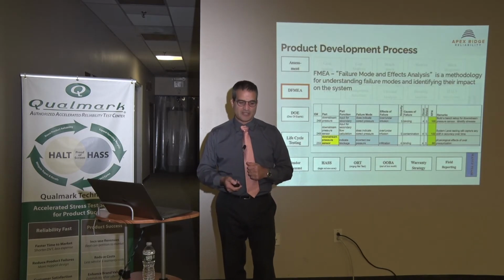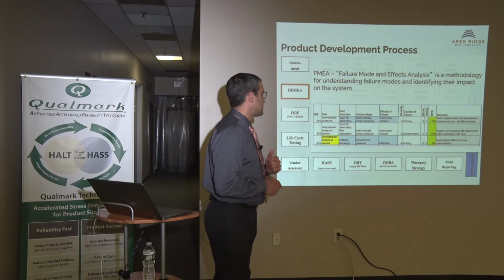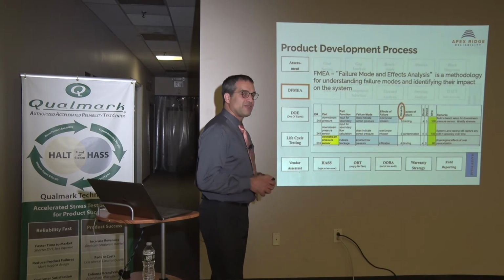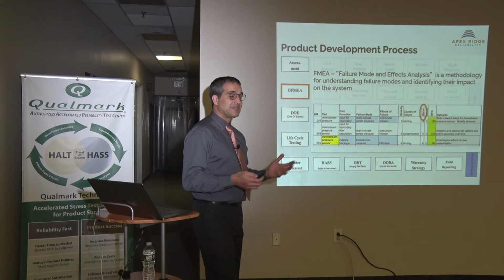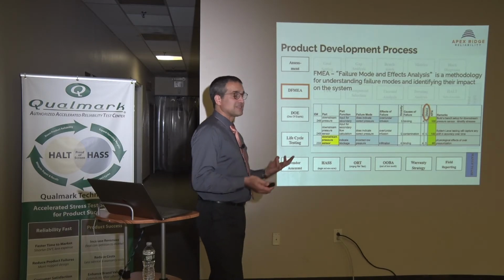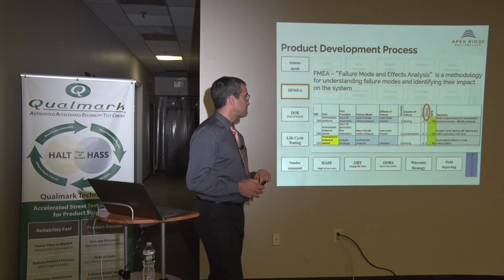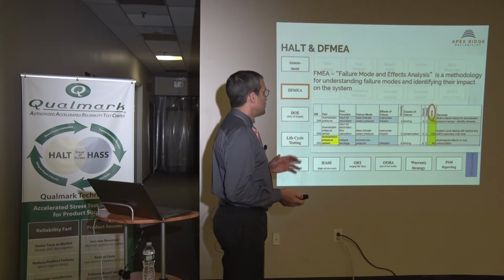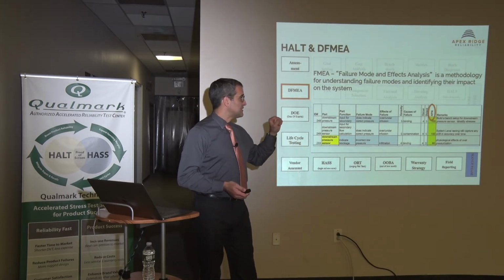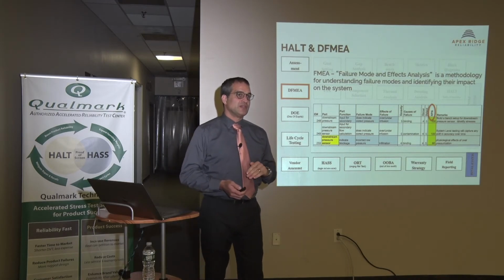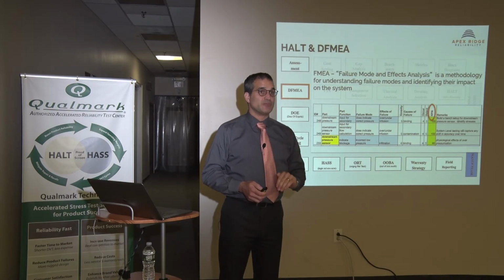So let's take one of these and talk about it a little bit. Let's talk about FMEA. How could they possibly interact with each other in a specific example? Well, we have the key quantitative parts of FMEA. You have the severity ranking, likelihood of occurrence ranking, and the detectability ranking for a specific possible failure. And this leads to the RPN number, which is the risk priority number, which is the product of the other three numbers. And this is the number that in the end we sort from greatest to least for each of these line items. Now we know where we should put our resource.